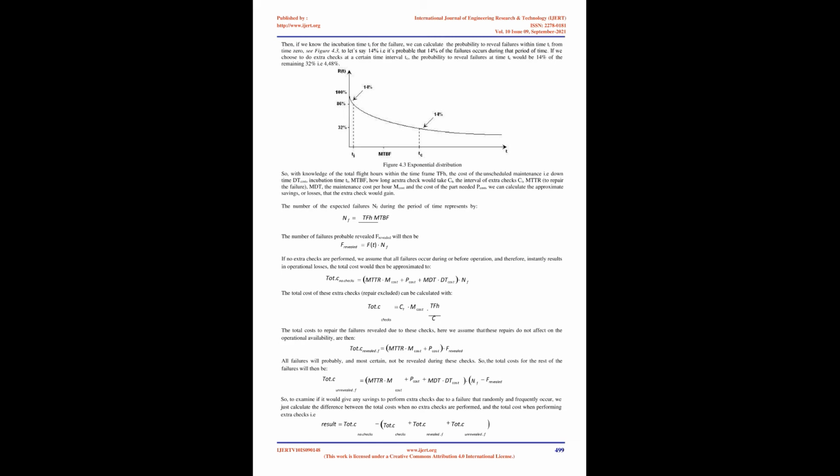Analysis of preventive maintenance. There is a need for more information than MTBF to be able to say something about the outcome of, for example, if extra checks would be profitable. So other measurements which were calculated and approximated were MTTR, MDT, cost of the part needed, cost of repair/hour, labor, facility, and VAT, incubation time of failure, and finally, the cost of operational losses due to downtime.